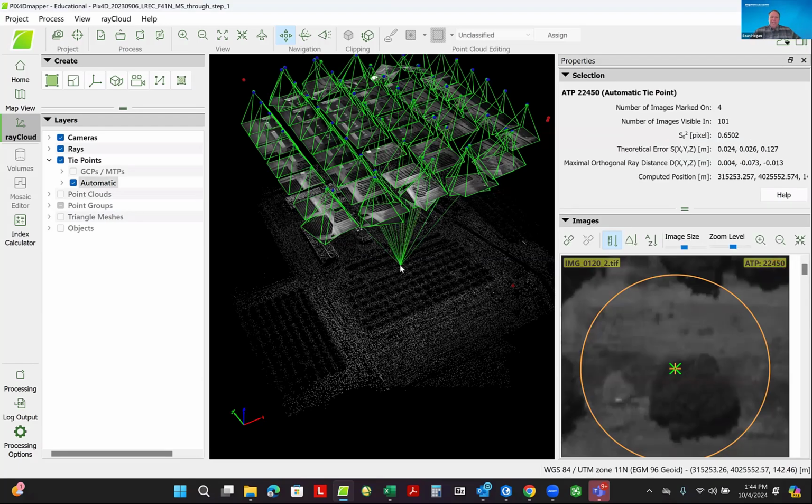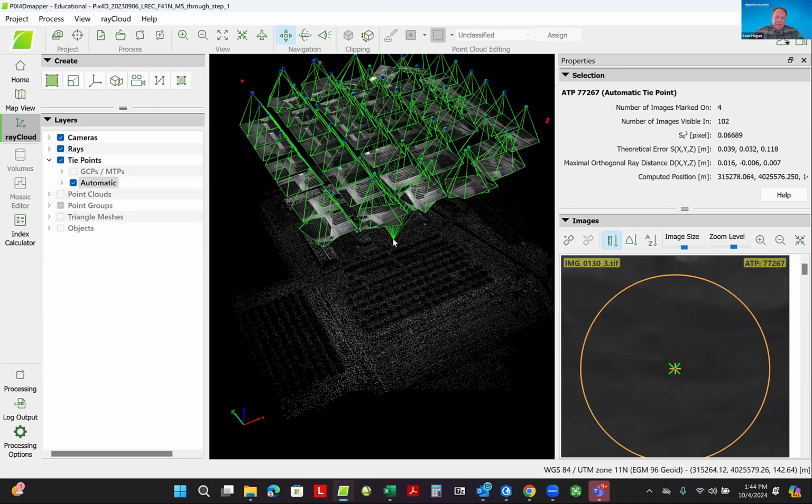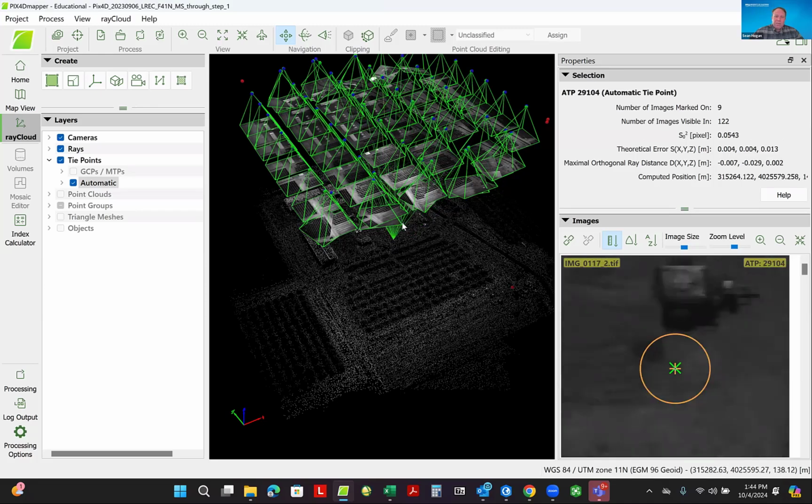If I click on this, the software sometimes, at a minimum, you have probably 10,000 ground control or 2D key points to lock the images together. Sometimes I've seen over 100 million before that'll be used. Well, the relative geometry of all of this point to this point to this point is calculated within the software. And based on those geometry calculations is how the software determines that this blue point really should be shifted a little bit to the side based on the angle of the pictures to the ground relative to all the rest of them.